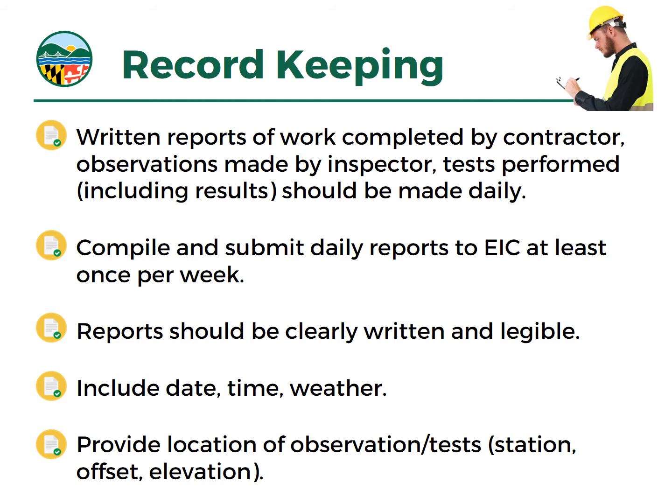Of course, reports should be clearly written and legible, and that's important because we might refer to them later on, 1, 2, 10, 20 years later down the road when we're looking to make a repair on a dam. We might need to know how it was constructed, so typed reports are preferred. We should include the date, time, and weather.